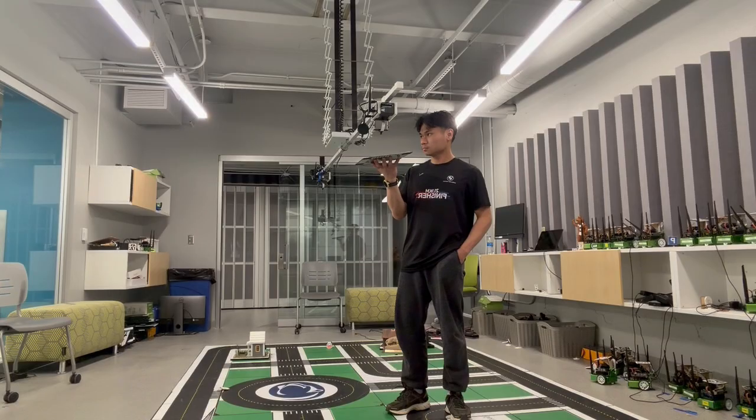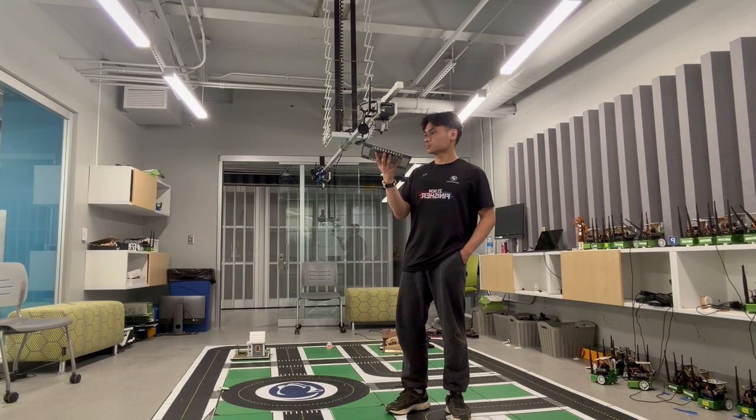In Lab 3, we used a second JetBot to detect the position and direction of the first JetBot on a road map using AprilTag markers. First, we captured multiple images of the bot from different angles. This helps us get better samples for calibration. Then we run the code to compare images with distortion and without distortion, so we can correct the camera view.